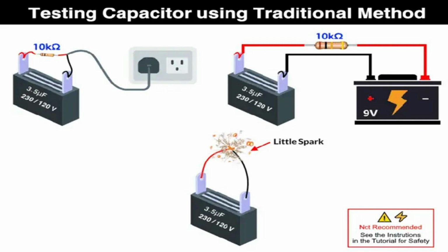Optional. Now safely connect these leads to 24 VDC or 230 VAC supply for a very short period, about 1 to 4 seconds, or for a short time where the voltage rises to 63.2% of the source voltage. Remove the leads from the 24 VDC/230 VAC supply.